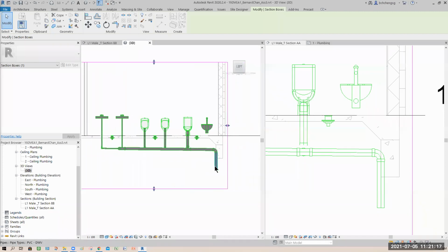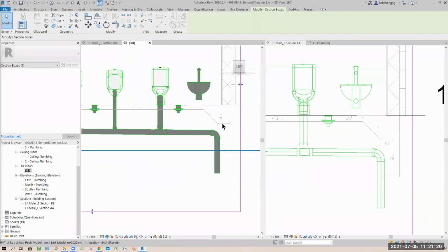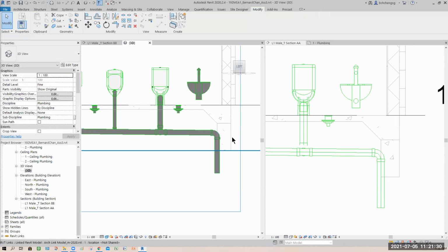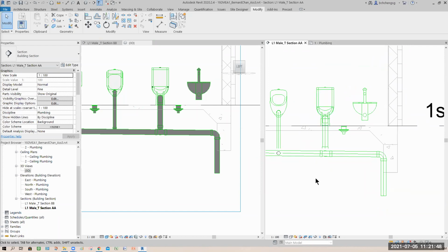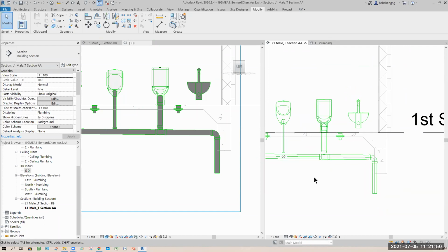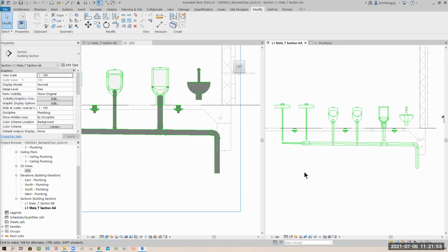You can't get your sanitary pipe clashing on this. At least it should go up from here. Fine, they can drill a hole, but not like this. Okay, this is the supporting beam. You cannot hack a beam. No way. So sad to say, I've got to redo all over again. I'm going to cry. So you guys, same as me, right? Yes. So at least now you understand why, right?